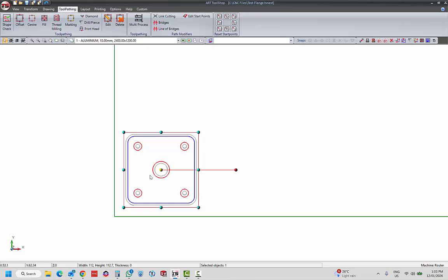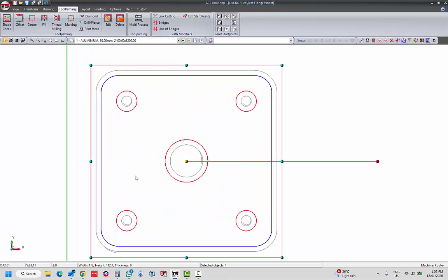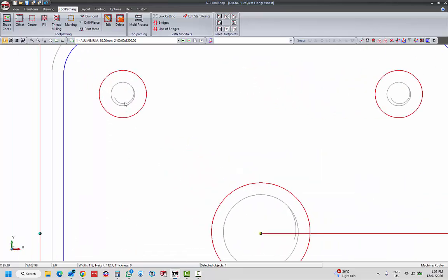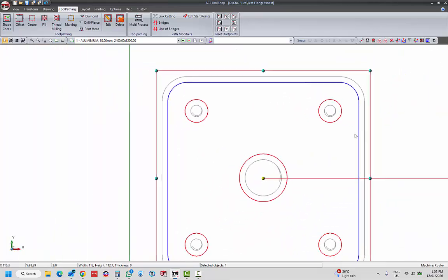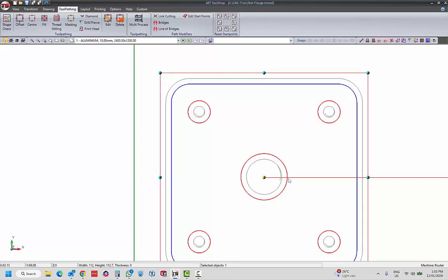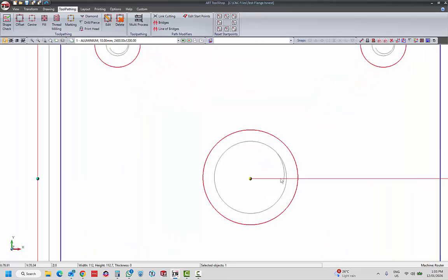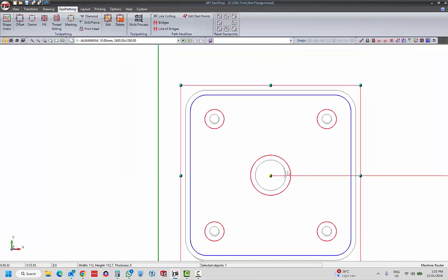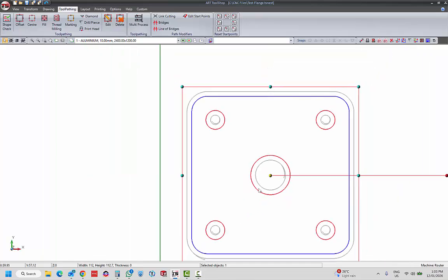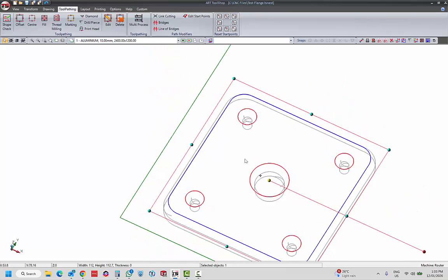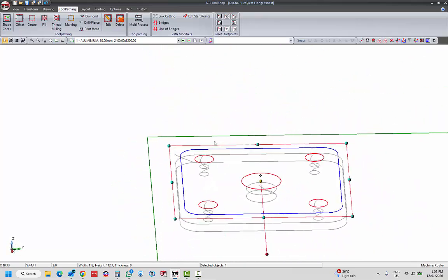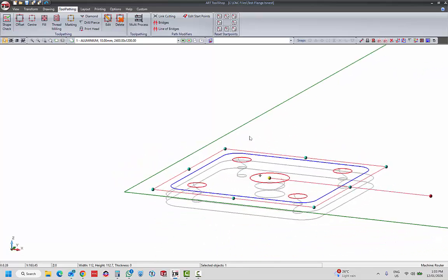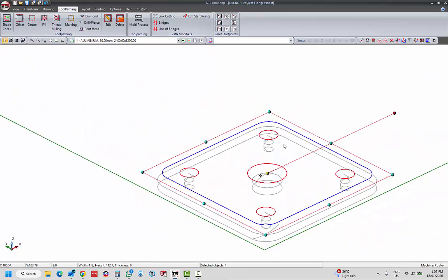Note that you can apply toolpaths to a whole sheet of parts at the same time. You can see that ToolShop has added the toolpath to the part. This is the actual path the cutter will follow. If you look closely, you can see the follow the side lead-ins coming in at 5 degrees. Next, I'm going to place my mouse pointer in the center of my part and click and hold the center button. This is the orbit function, which lets you look at things in 3 dimensions. Dragging the mouse around will move the viewport around the object.